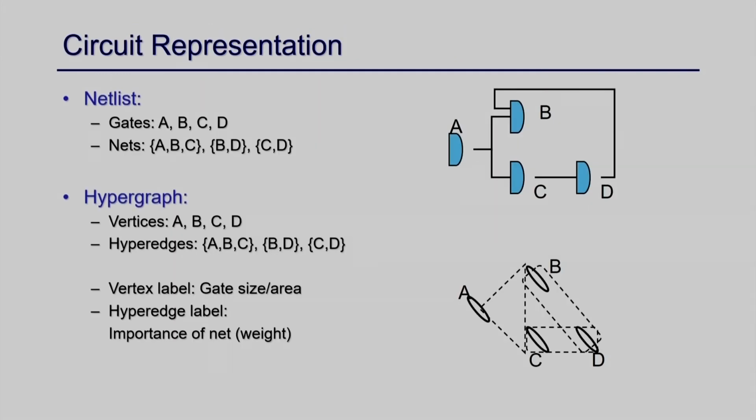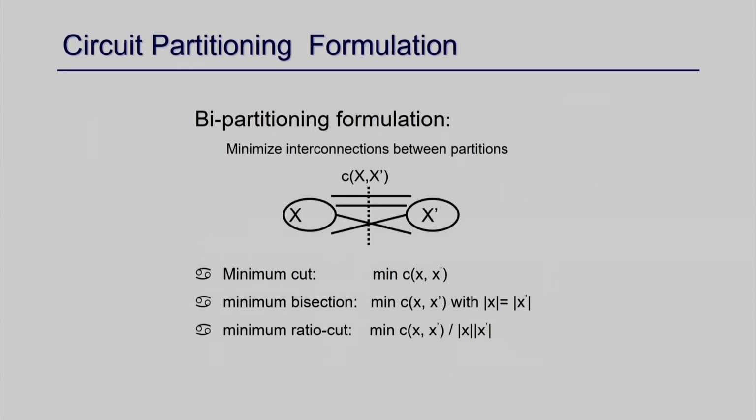So that is what is important. If you formulate the circuit partitioning problem, our objective is to try bipartitioning. The partition can be anywhere: it can be k-partitioning, where you partition into k components. If it is bipartitioning, you make it two. You can do it recursively: I break the whole circuit into two, then each of those is again split into two, and this is a kind of bipartitioning, right?